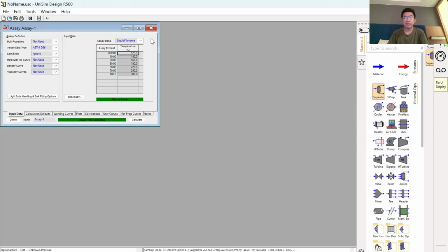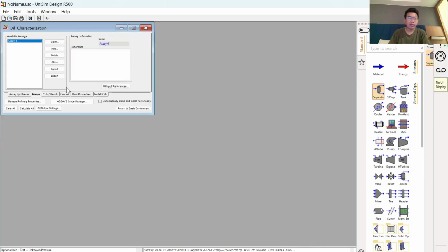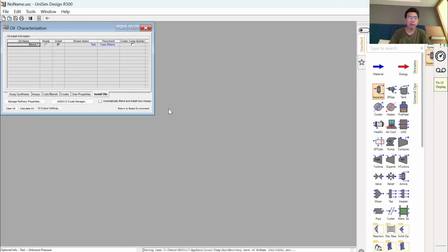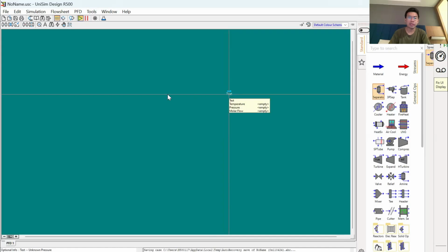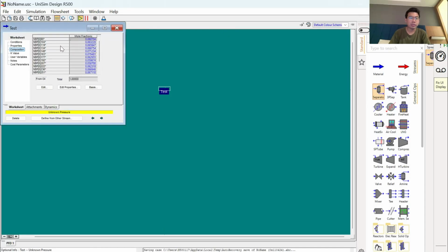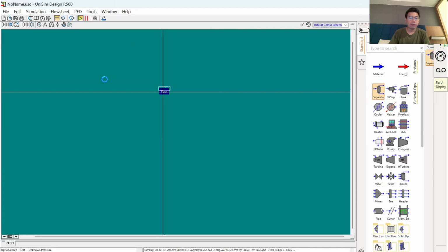If you aren't familiar with Oil Manager, please do watch one of my old videos that discusses Oil Manager and come back here again. After I calculate, I put it inside a blend, then I install the oil. So I have one stream now, which is the test stream, and this stream already contains the composition from the Oil Manager. I will fully define this stream.